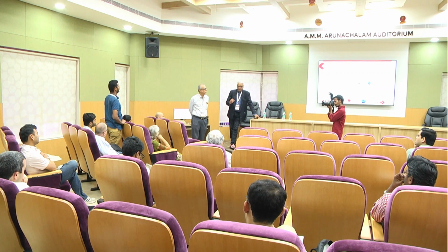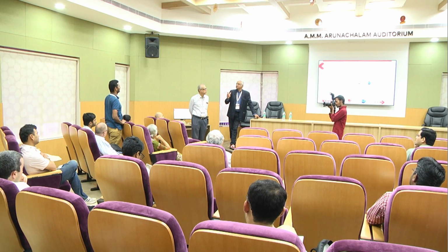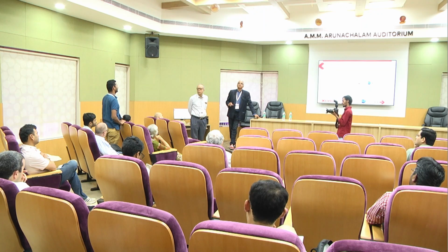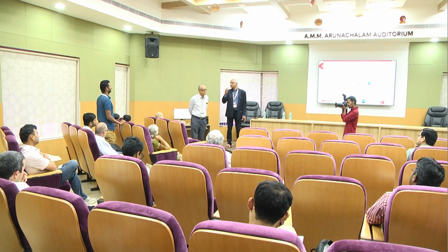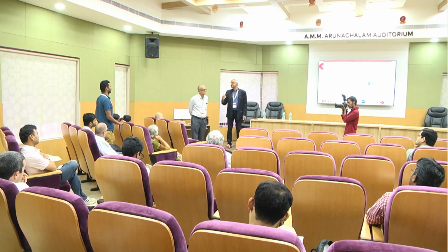Your question is how I can identify if it's surface traps or buffer traps, no? That we have done by TCAD simulation. We have put traps everywhere, also in the AlGaN barrier. We have seen that only when you put surface traps, silicon nitride and GaN cap, and buffer traps, you obtain the Y21 simulation.